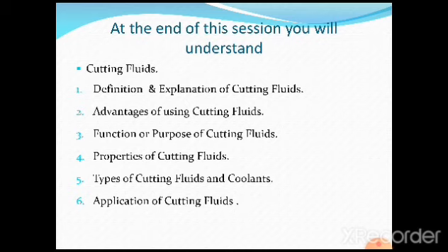Before I proceed with today's session, I wanted to revise one important thing. Whenever we want to carry out a metal cutting operation, it is very important that the temperature at the tool chip interface should be maintained very low, because if the temperature increases as the machining operation is in progress, then there is a formation of built-up edge or a false edge, and the cutting edge of the cutting tool will start wearing out